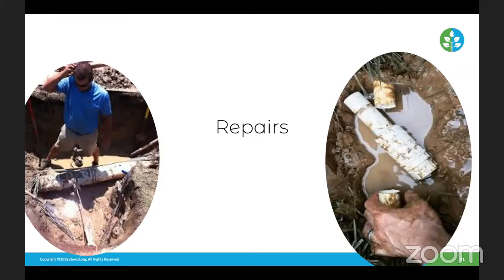And the issue with it constantly leaking is that it's allowing the diaphragm, the moving component of the valve, to not be completely closed. So there might be water seeping into your irrigation system. Indicators of that would be, let's say you have one sprinkler that looks like it has a lot of green moss, or water is just barely leaking out of it and it looks like it's constantly moist. That's an indicator that your valve is not closing completely.